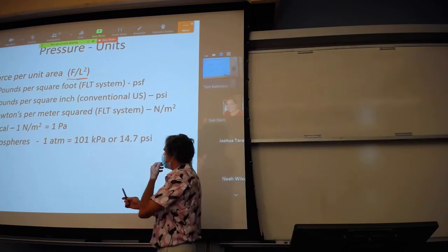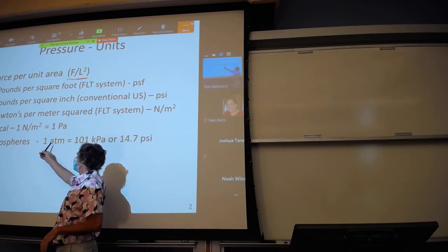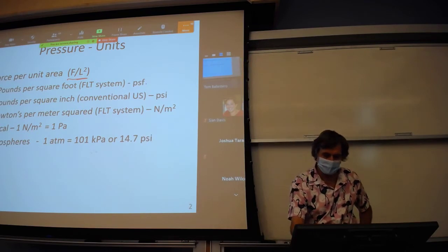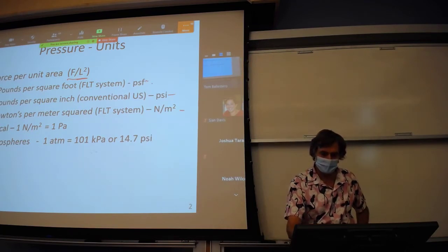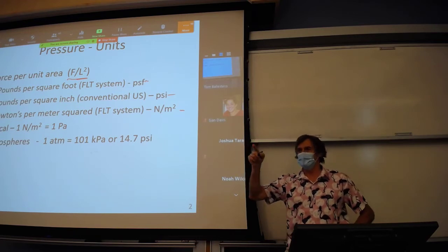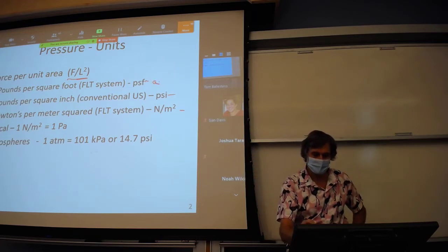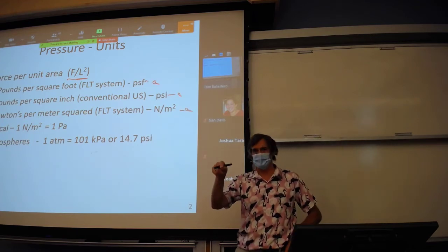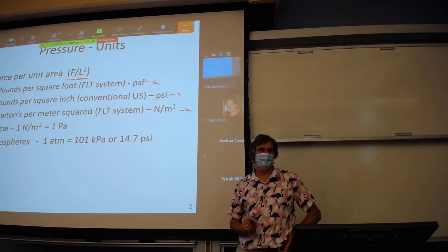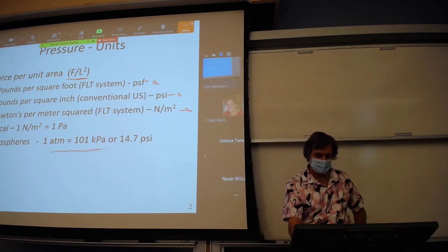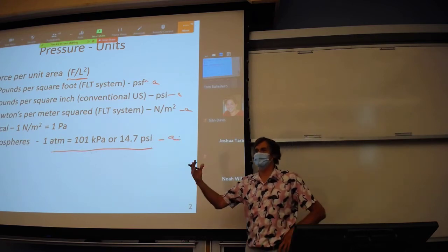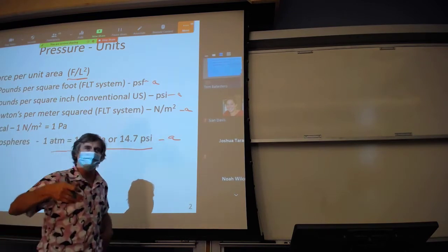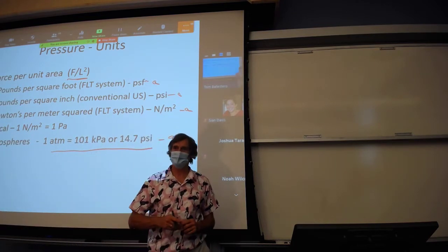Whereas whenever we talk about absolute pressures, we would take any of those units, whether it was PSF or PSI or Newton per meter squared, we know that those are in local datum. If they're followed by an A, then you know that pressure is being reported in an absolute pressure measurement datum. Understand? And whenever somebody gives you atmospheric, that is in an absolute pressure measurement datum because, again, atmospheric pressure in a local datum is 0. Okay?